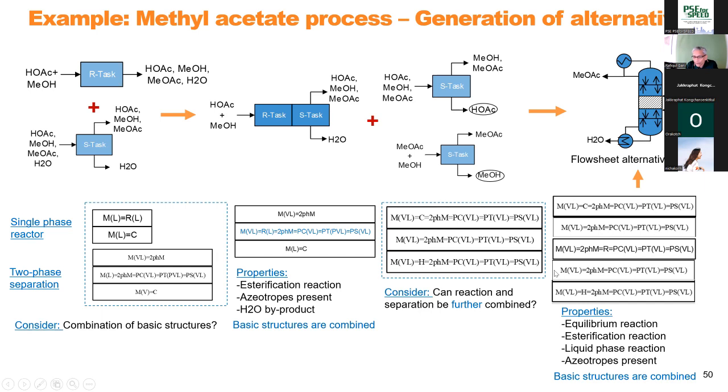And the nice thing about it is that we can have as many of the reactive stages and the non-reactive stages. By increasing this for more than one, we can keep on increasing until we get the product purity we want. And then we know how many stages are here, how many stages are here, how many stages are here, what is the condenser duty, what is the reboiler duty. And so that is the way to convert any process flow sheet to a reactive distillation.